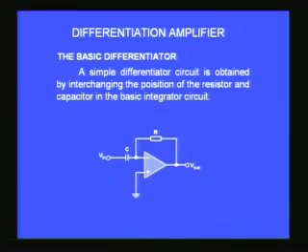I will try to explain to you how we can do that when we actually go to the circuit. So a very simple differentiator circuit I have shown here using an op amp, where again the same network which I discussed a moment ago is being used. You have a capacitor and a resistor. In this circuit the non-inverting input is actually connected to ground, and therefore the minus side becomes a virtual earth, and therefore whatever voltage I apply is actually between this and this point, and that means it is only across a capacitor.